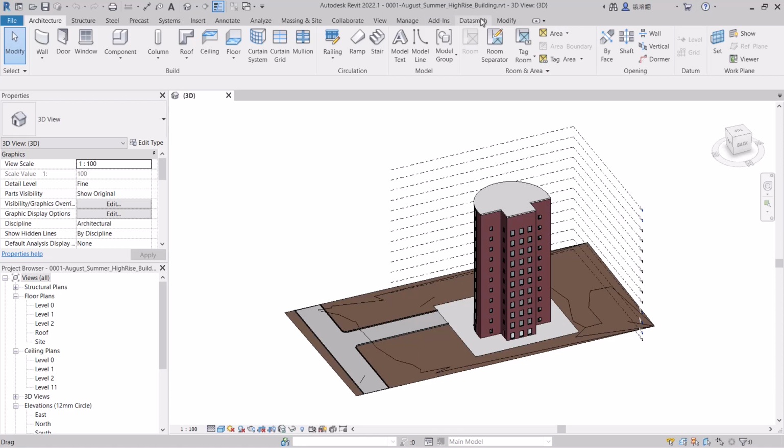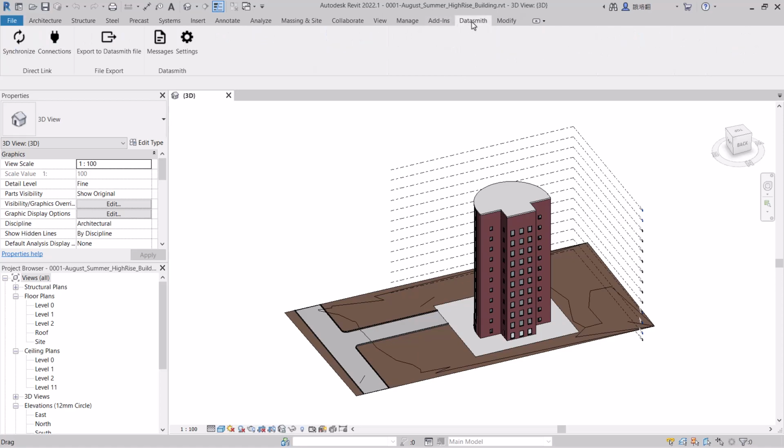You can go on to download it, and then once you're done downloading and installing that direct link, you have the Datasmith Twinmotion link like a plugin in Revit, so you can use this menu to export your Revit model as a Datasmith file. It's like export, but within export for Twinmotion. So we're going to click the export to Datasmith file.